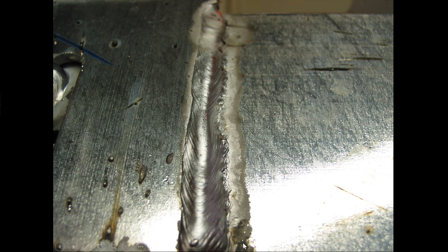Now here's a typical weld that's had some gas problems, I believe, and you see this often where there's become turbulent. Now, see this edge that's coming like this? There's a bunch of different reasons to have that, but in aluminum, often it's caused from dirty nozzles. Dirty nozzles build up and the gas starts to come out erratically. Sometimes the gas will come out if the hole closes up, if it's not reaming properly. It'll cause the gas to come out either with greater velocity or with turbulence. And when it comes out like that, it picks up some air.